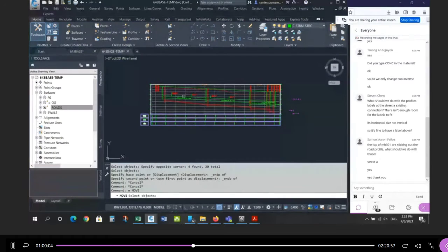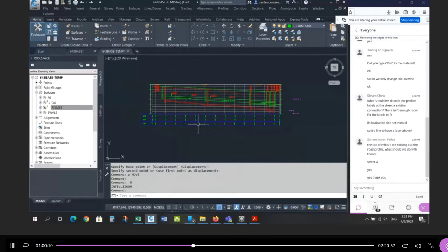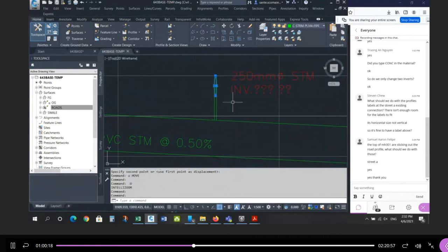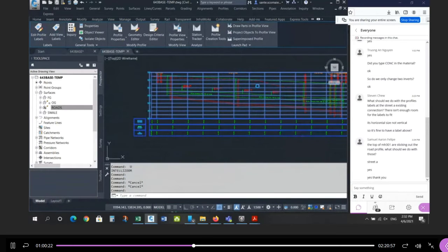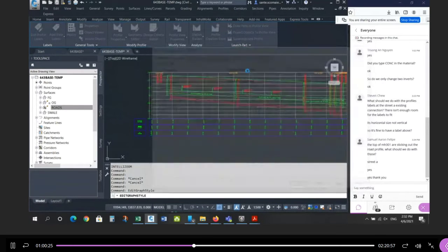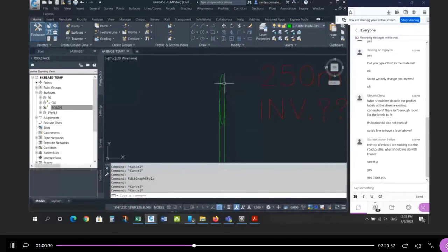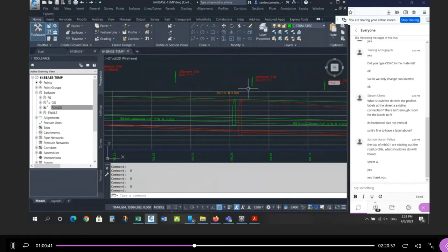So just be mindful that when you draw something using AutoCAD, it's not part of your database, it's static. So if you make changes to the data, you may have to adjust the profile. The other thing too is that when you draw these, remember this is vertically exaggerated 10 times. If I change the scale factor, if I go back to profile style, if I change this to 5, then these are all not only in the wrong spot, but too big. The top needs to look like half the size. It'll get squashed vertically, right? So now you have to redraw that. So scale is a bigger problem than a shift up and down.